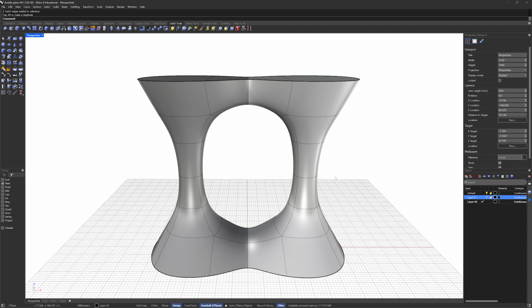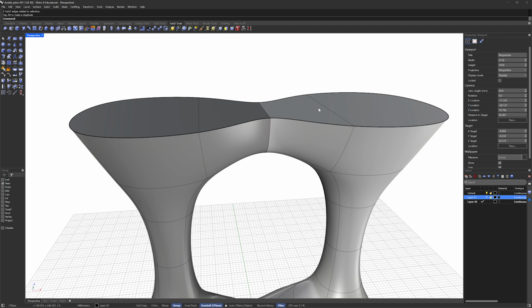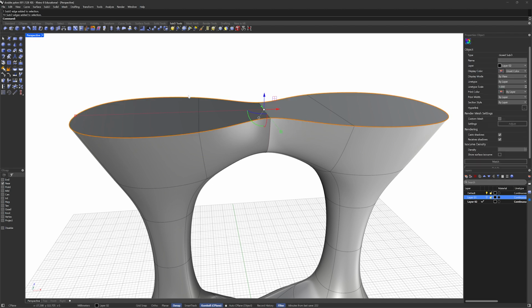So right now we've got this crease, which is razor sharp. You probably want to, at some point, fillet this if it's going to be printed. But I've got a better thing to do. Let's first select this edge, and it should be continuous now that it's all blended together. So I'm going to double click, and yep, it went all the way around.